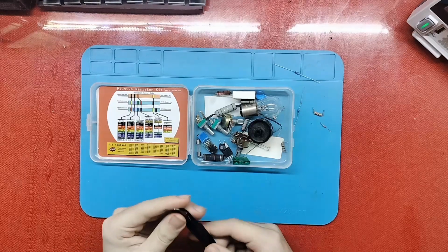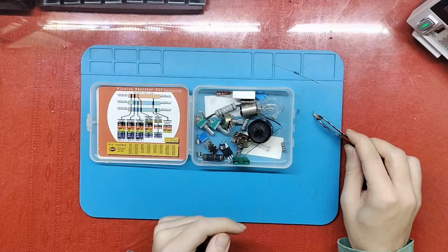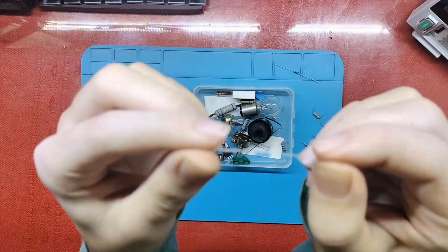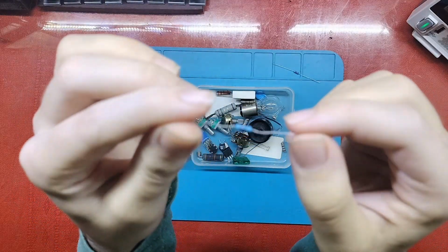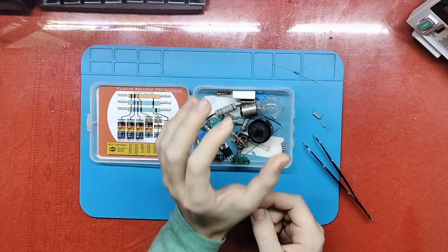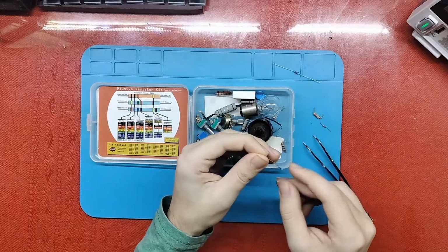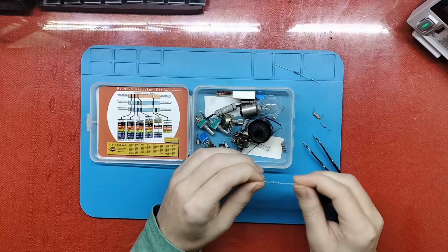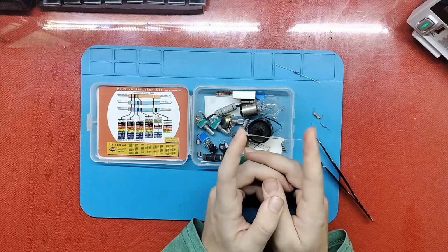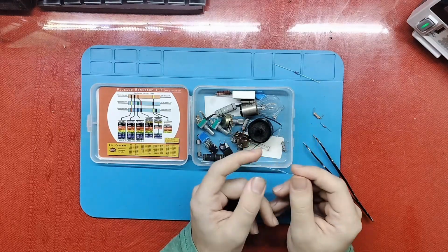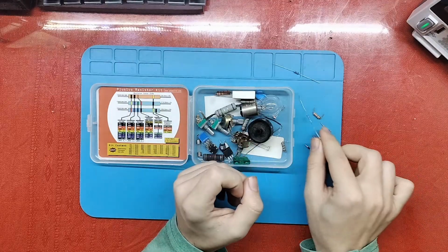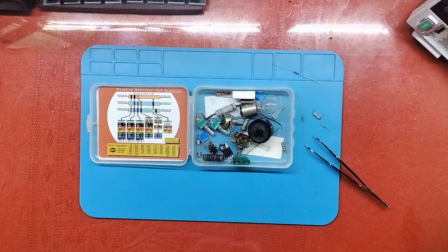Now, there are a lot of types of resistors. The most common one, as shown earlier, is this type. I don't know if the camera focused, but it's this little axial package. These are non-variable resistors, as they're known, which means they technically and ideally always have a fixed resistance. Now, if you want to find the resistance, you can either go with the color code, which I should have a chart around.